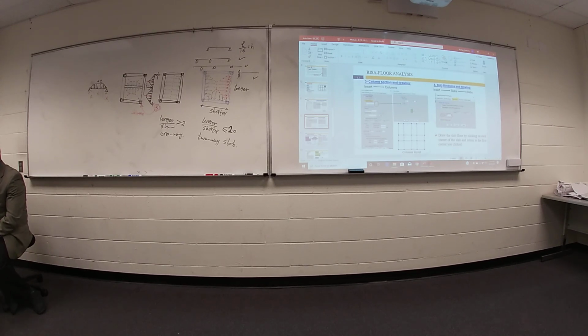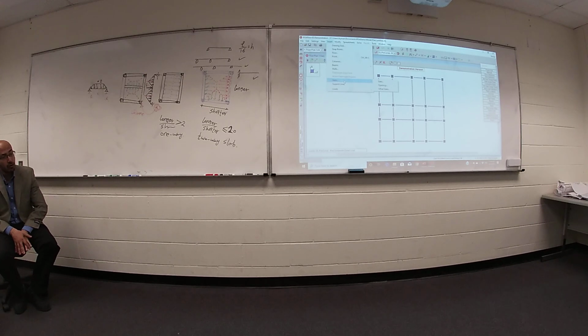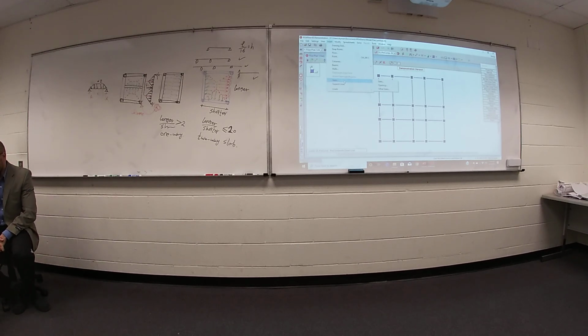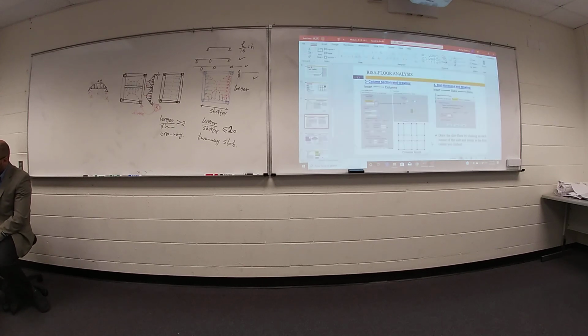We need to define your slab thickness, 5 inch, and then draw your slab. Where? Insert. Everything from insert. This time I can use slabs. We are looking to draw slabs. So insert, slabs. First, what is the thickness? This option. Your thickness, 5 inch. Go back to draw your slab. Apply. Start to click at each corner of your slab. Before starting, I would like to define something.